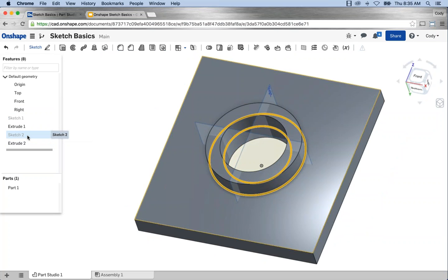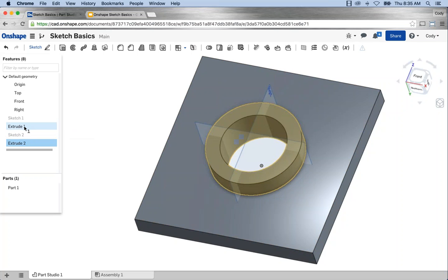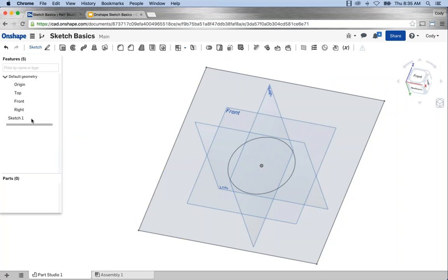So the use command in general is a very powerful tool. I highly recommend, if there's any situation where you can constrain it to a previous feature, oftentimes there's a benefit from doing that. It's a much faster change. When you make a design change, everything rebuilds as opposed to having to go through each feature manually. So just a tip on use in general.